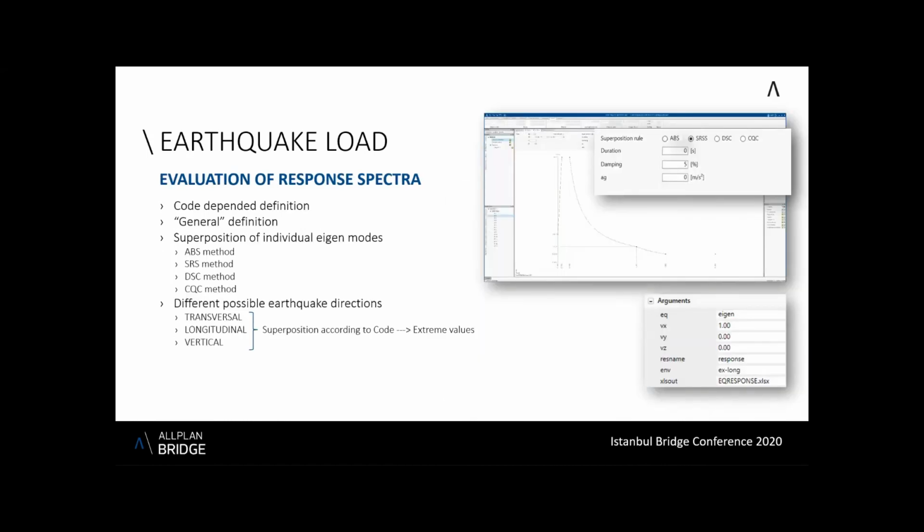In case of an earthquake, the actual extent of the different natural modes is dependent on the direction of the seismic waves, the ground accelerations, for example, the corresponding mass participation, and the damping behavior of the structure. The analytic solutions for typical structures and unique impacts are provided in the design codes as relevant response spectra, specifying the relevant proportionality factors for the individual eigenmodes dependent on the natural frequency.